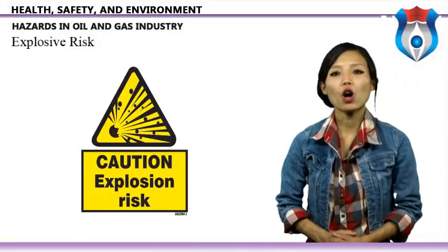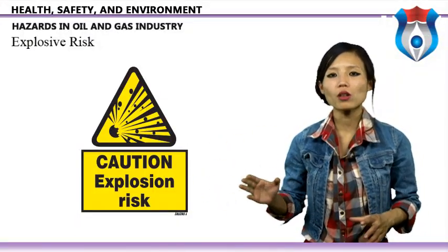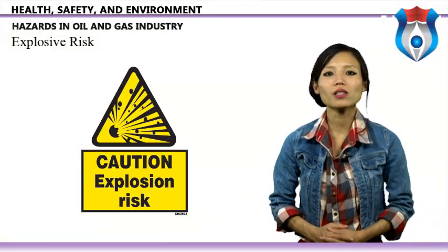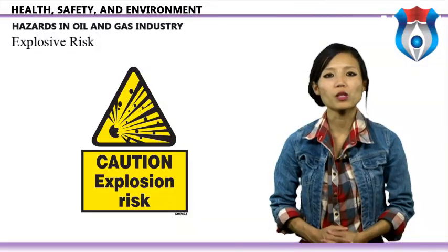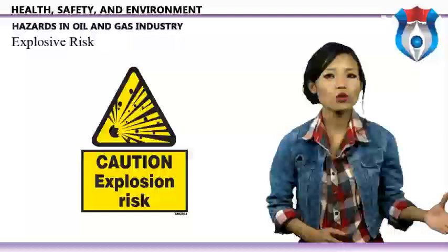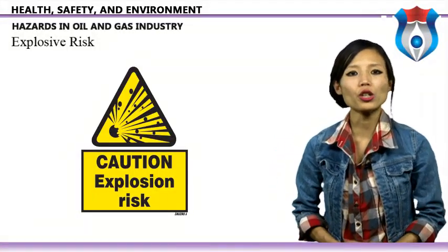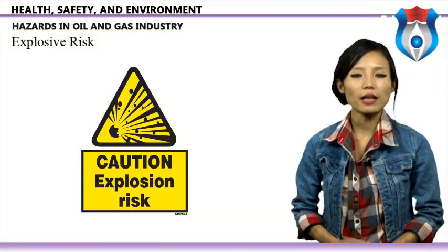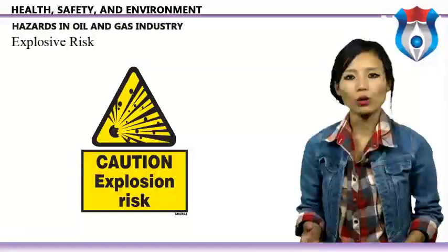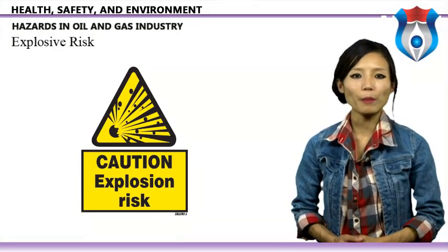Explosive risk. In order for gas or vapor to ignite, there must be an ignition source, typically a spark, flame or hot surface, and oxygen. For ignition to take place, the concentration of gas or vapor in air must be at a level such that the fuel and oxygen can react chemically. The power of the explosion depends on the fuel and its concentration in the atmosphere. The relationship between fuel-air ignition is illustrated in the fire triangle. The fire tetrahedron concept has been introduced recently to illustrate the risk of fires being sustained due to chemical reaction.